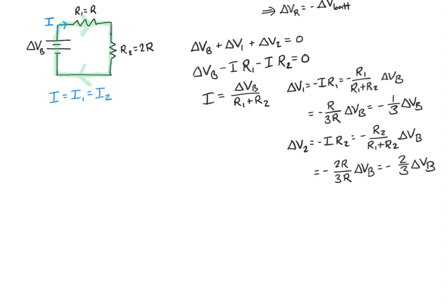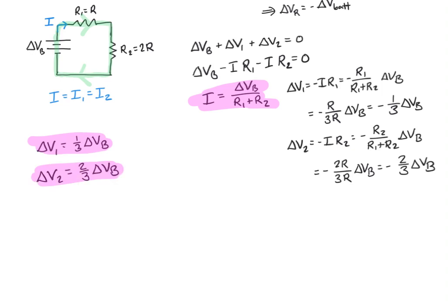So generally speaking, if we're talking about what is the voltage across resistor R1 without any additional context, we would always give the positive number. The direction, the sign, whether it's plus or minus, would then be inserted afterwards by hand based off of whether or not you are choosing to go in the clockwise direction or counterclockwise direction, or rather, whether you're going in the direction of the current or in the opposite direction of the current. So this gives us our final tally. We've calculated the current through our circuit, and we've calculated the voltages across resistors R1 and R2. And that is everything that there is to learn about this particular circuit, other than power.